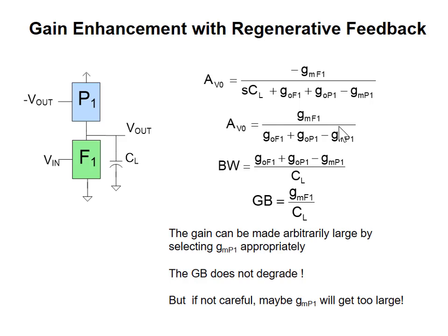And why is it so low in frequency? Because the gain bandwidth product is constant. Now, that's not the reason. Why is this pole so low in frequency? What did we talk about the last 2 lectures? Because the compensation capacitor has to be small. You have to have a big pole spread to get acceptable performance. You don't know how to push those high frequency poles any higher. We know how to pull the low frequency pole lower. Okay? So why is it low in frequency? We have to put it down there to be able to get acceptable performance in feedback.